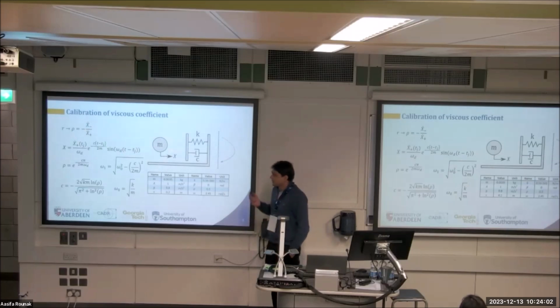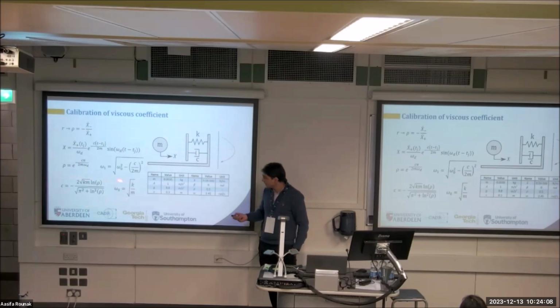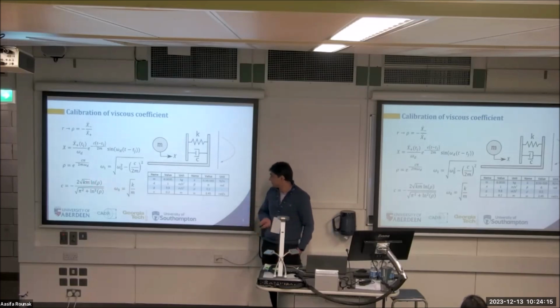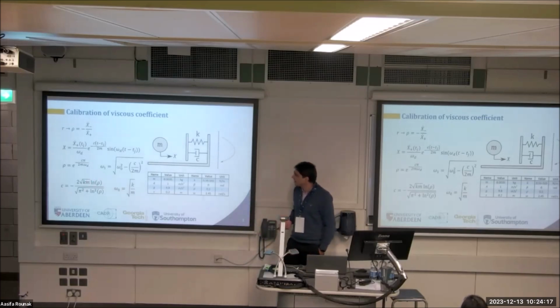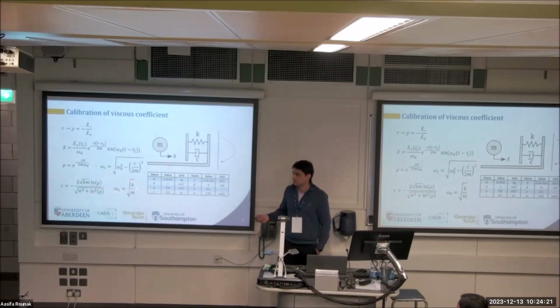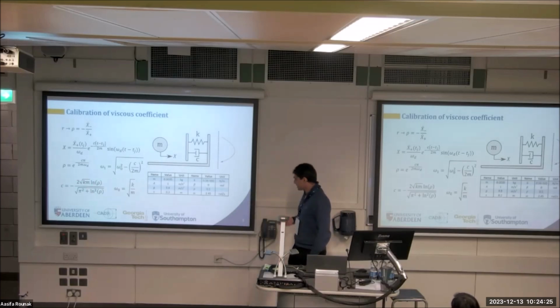And if we do the calculations without any kind of excitation, we can then find a relationship between our damping coefficient and this pseudo restitution coefficient. And then we can set this calibration by setting our pseudo restitution coefficient equal to that of the hard impact model. So we do this calibration.